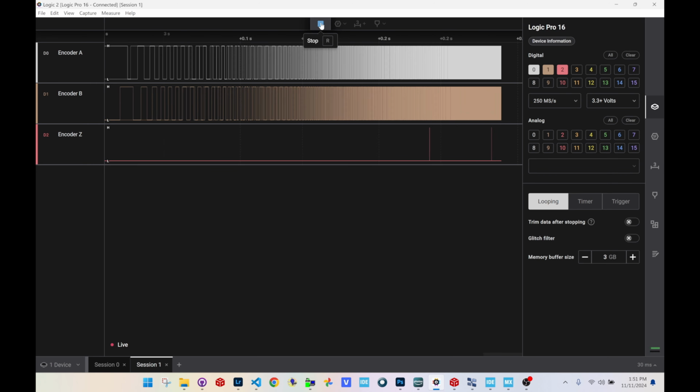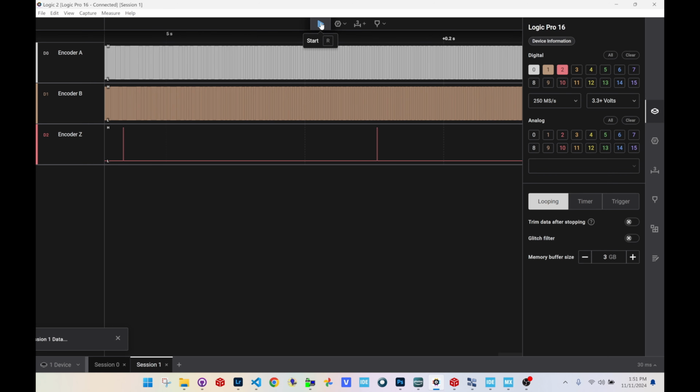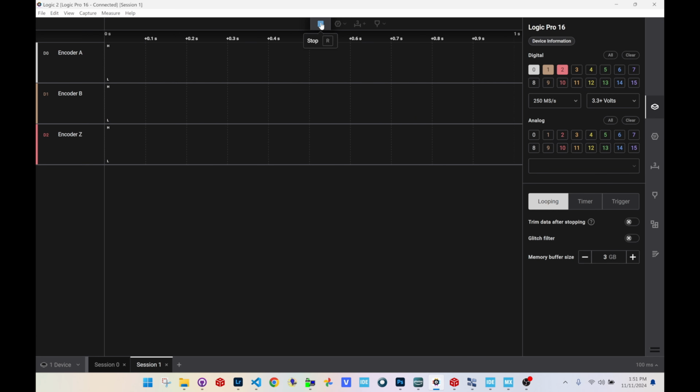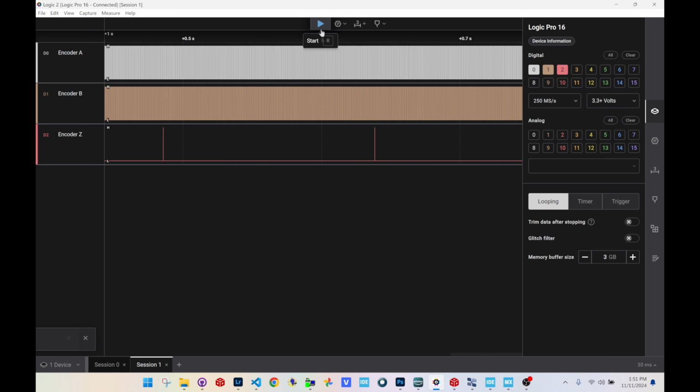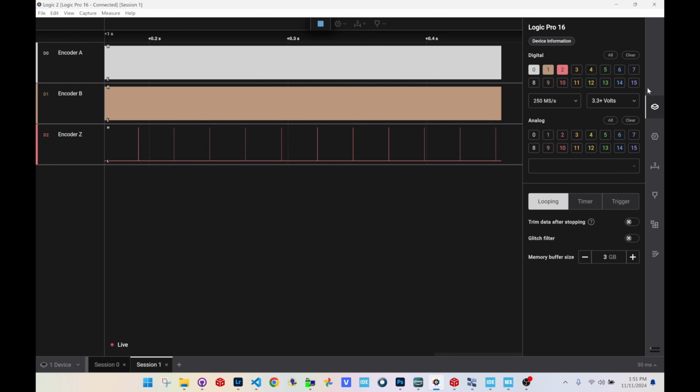And now that we're using the encoder to know the rotor position, we can commutate the motor. All we need to do is just lead or lag the sinusoidal waveform. That'll cause the rotor to spin. Here you can see that the 0 signal of the encoder can be used in order to calculate how fast the rotor is spinning.